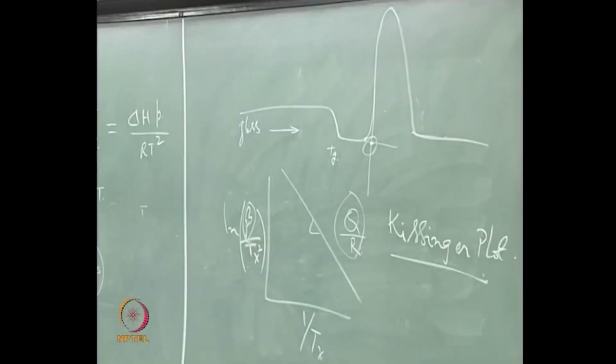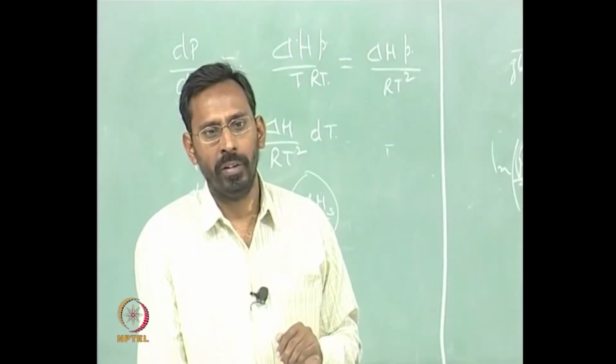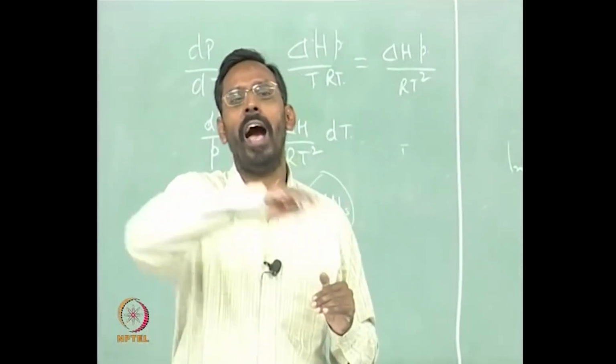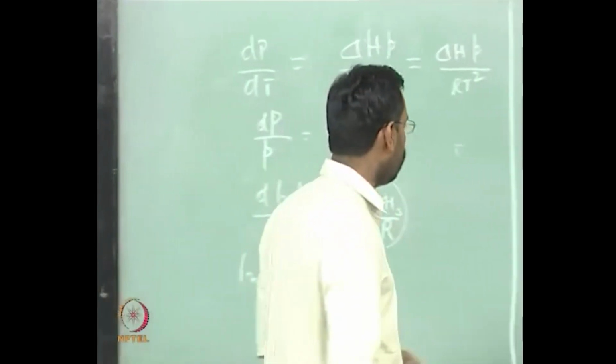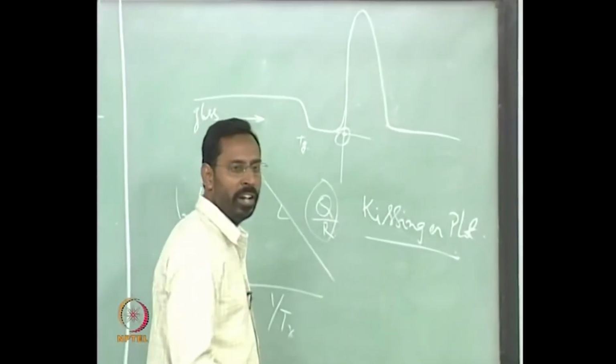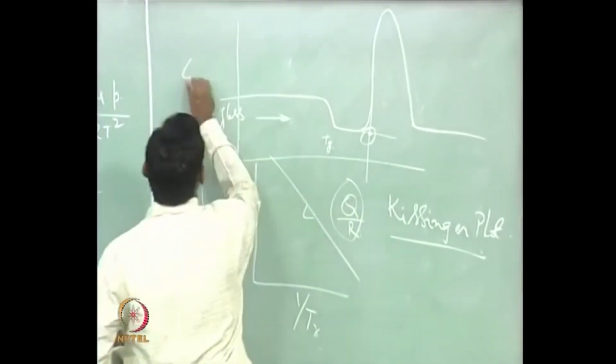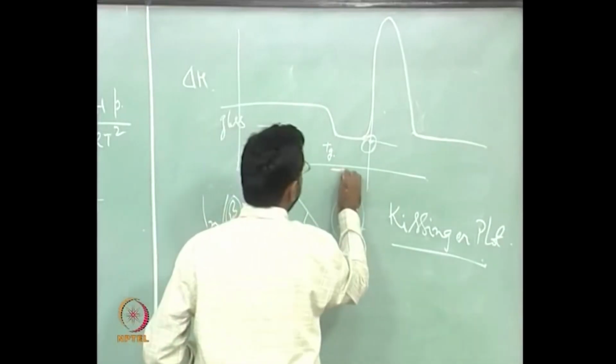What do we mean by athermal kinetics? It means you are doing it as a function of heating at different rates. You can also have what is called isothermal kinetics. That means at a given temperature you try to have the transformation taking place. In principle, if I do the same transformation in a DSC, what we plot is delta H versus temperature.